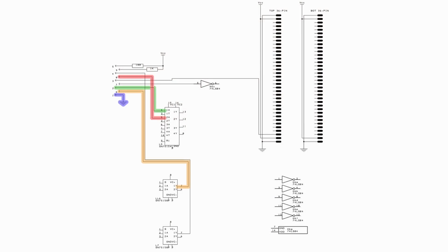Now, the multiplexer card itself is a bit more confusing. We have essentially 9 pins. 2 are tied to 5 volts through 2 resistors, 1 is tied to ground, and 1 more is tied to negative 12 volts. That leaves 5 pins that have to do with communication. Pin 6 is receive, pin 8 is transmit, and pin 2 is our CTS signal coming from the terminal. That leaves 2 unknown pins.